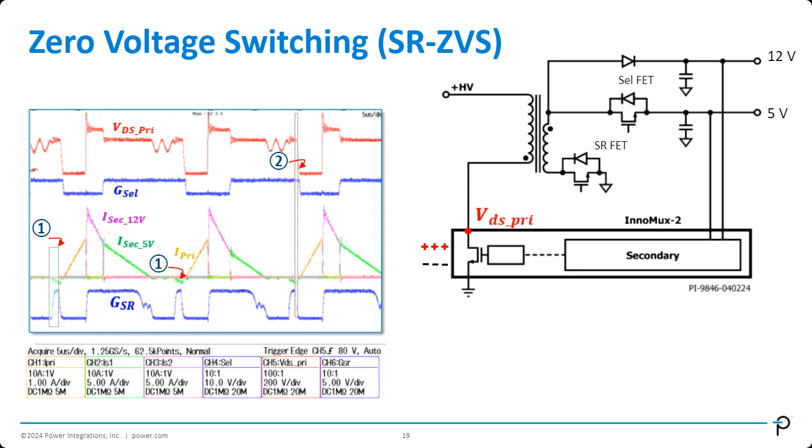Okay, so timing as in how long you need to turn on the SR FET and how long you need to let the voltage decay over here and over here. These, like I said, are all adaptive, but mainly the amount of time that you need to turn on the SR FET depends on how much energy you need to discharge over here. That's related to the input voltage, the magnetizing inductance, and the equivalent capacitance across the switch over here. So basically, you need that information.